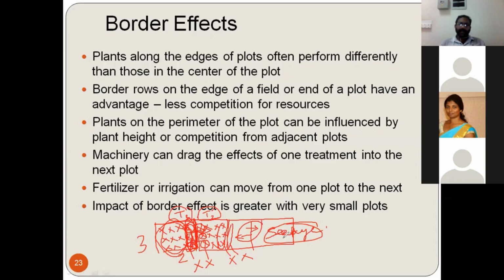The second way is how we can reduce the seepage, how we can avoid the seepage. We can avoid the seepage by putting a polythene underneath. That is also possible. So people do some research, but in fixed studies like in the Philippines, the Rice Research Institute has concrete walls between the plots, permanent concrete walls, so that there is no seepage, especially for this kind of study, right? Fertilizer studies. So we have to stop all this.